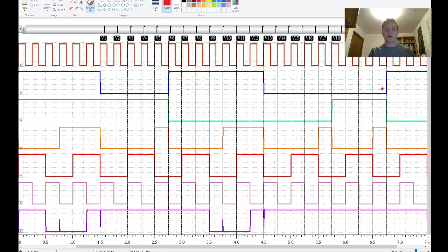It was correct when it traveled through all the different states from V1 to V22, and we see everything just restarting again. We did see that D was the correct output for all the correct inputs, and these logic hazards here would be fixed if we went back and fixed the Boolean equations in order to account for them.